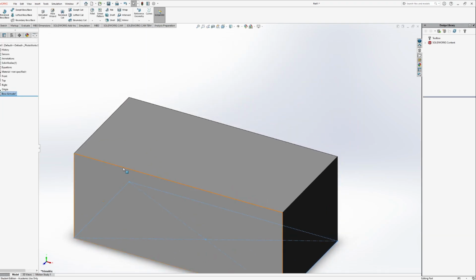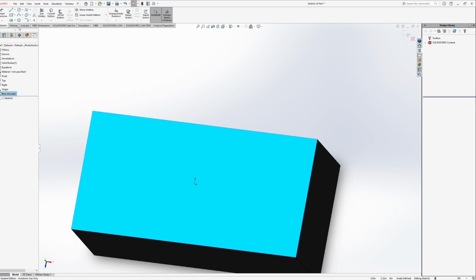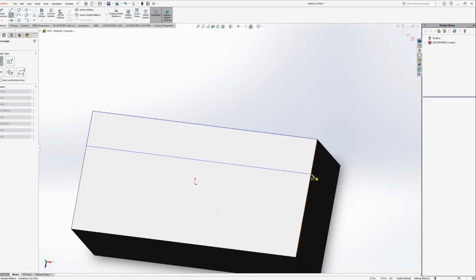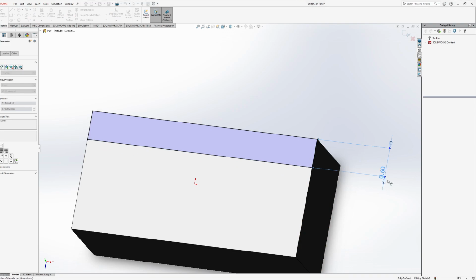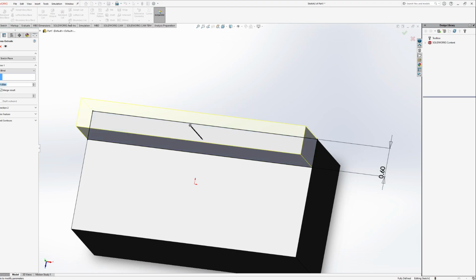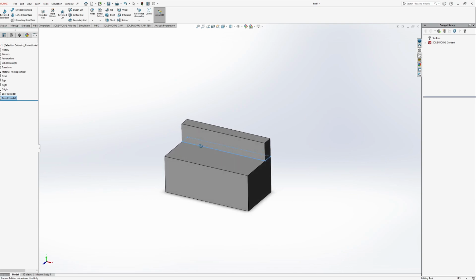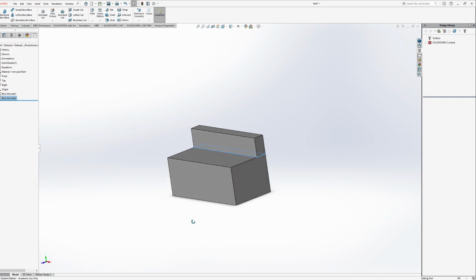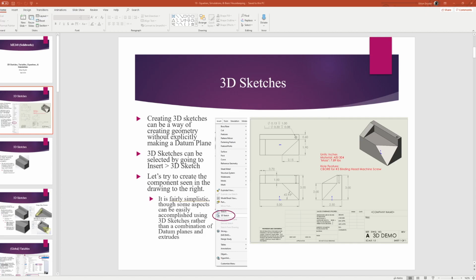And then we want to make sure that we can create that other smaller looking box on top. So we'll draw on this plane as well, and I'll make this a corner rectangle just because it'll be that much easier to create that box. It's 0.6 inches, and I think this was a 1-inch extrusion. Okay, so getting to this point really shouldn't be that crazy. We should have a fairly good idea of how to create this shape right here, and that's pretty much where we are in the PowerPoint as well.